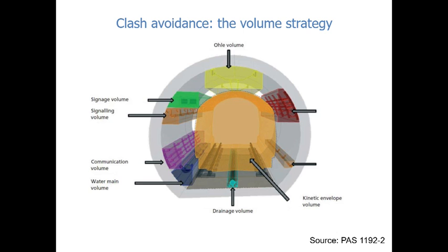Volumes allow you to reserve spaces without building the systems. So if you say this is where my communication channel volume will be, right? All the communication will run through this volume in here. So any volume intersects with this will be detected as a clash. Okay, that's which means that you're setting tolerance, between each volumes. Okay, so this is my, let's say, signaling volume. Okay, anything that's to do with signals will go in here.